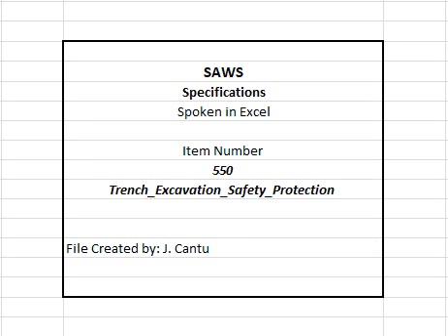feet. 2. If forms or other structures are installed or constructed in an excavation so as to reduce the dimension measured from the forms or structure to the side of the excavation to 15 feet or less, measured at the bottom of the excavation, the excavation is also considered to be a trench. 3. In addition, trench excavation protection will not be limited to these applications, but may be used whenever deemed expedient and proper to ensuing work.